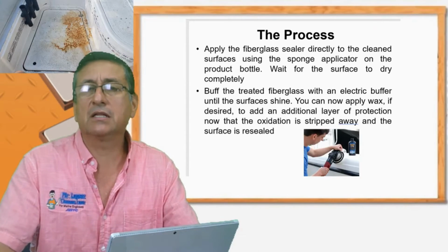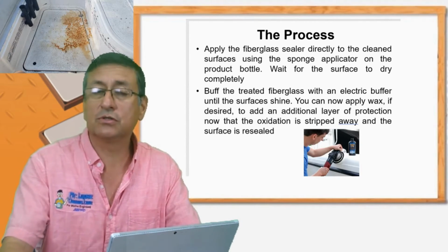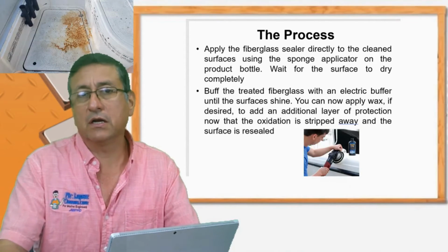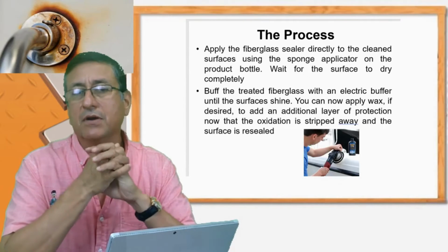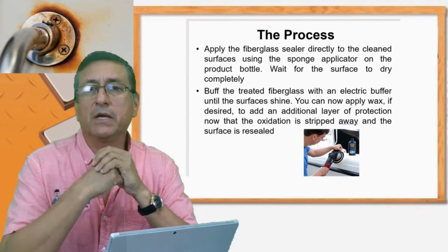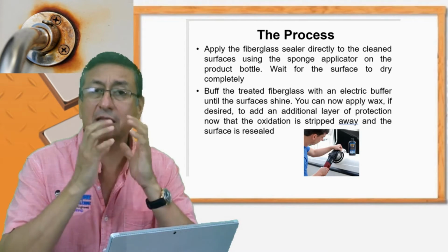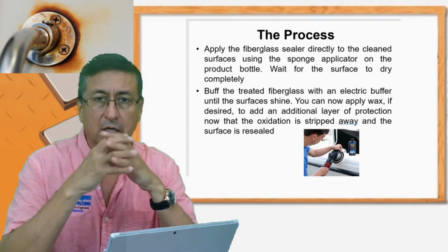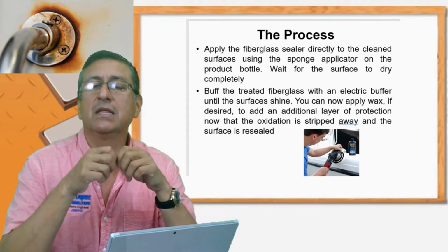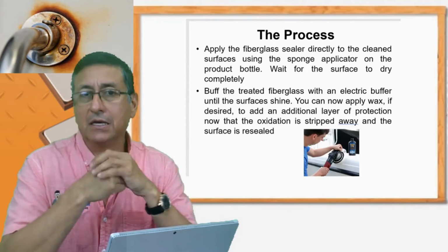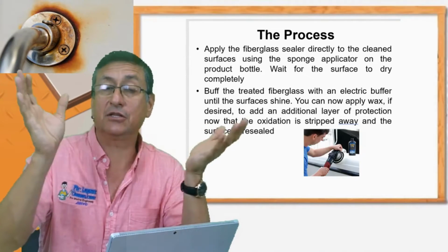This is cosmetic. There are a lot of people specialized in detailing, and they use those products to recover the fiberglass. But don't forget, the secret is to never install inappropriate hardware on the fiberglass structures, because at the end of the day you destroy the material, the fiberglass will be delaminated, and it's easy for the water to penetrate and destroy it.